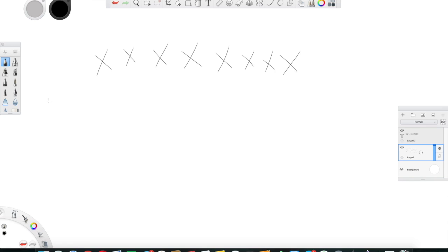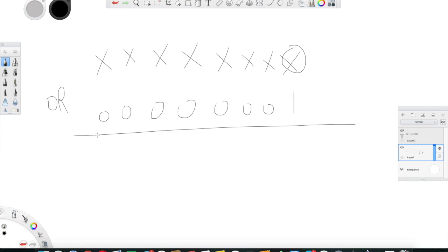I will be using an OR operation, and I want to set the least significant bit number 0 to 1. So I'm going to OR with all zeros, except the least significant bit, which will be ORed with a 1. So this will result in what? In x's. I'm not affecting the other bits. All other bits remain unaffected, and that's the embedded C programming concept.